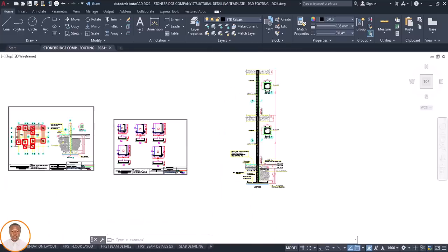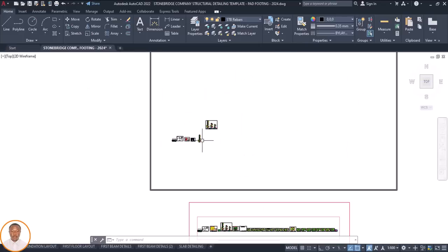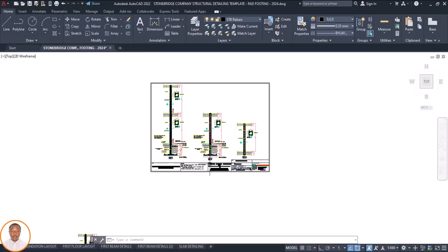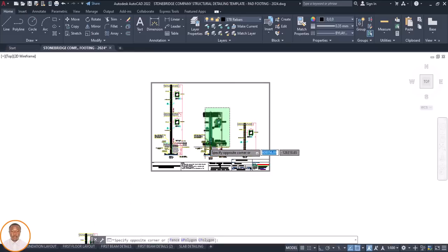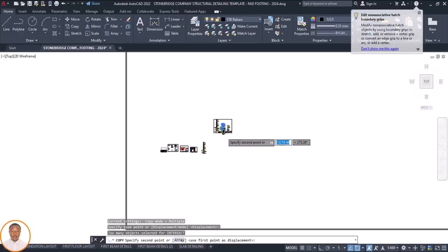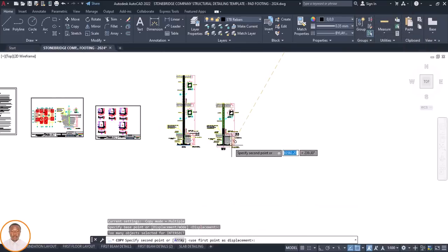Is that okay? I have to go to C2, which are not going up. Those columns that are terminating at the ground floor. Let me now see. You can see this one is terminating at the ground floor. So I'm going to take this one as this sample. K, then CP, copy, then take it again. Those ones that are not going up, I'll come to this place and also pick it and put it here. Is that okay? I just put it here.